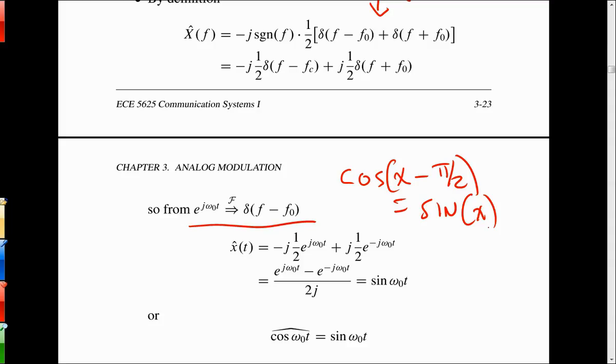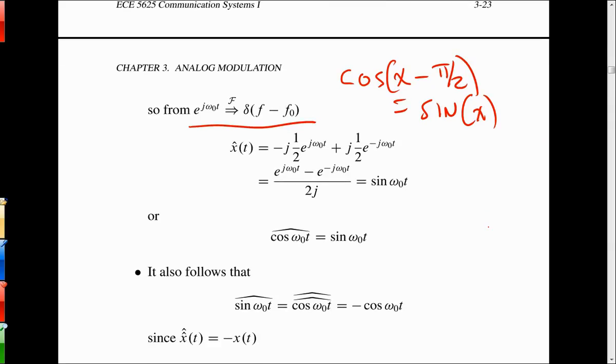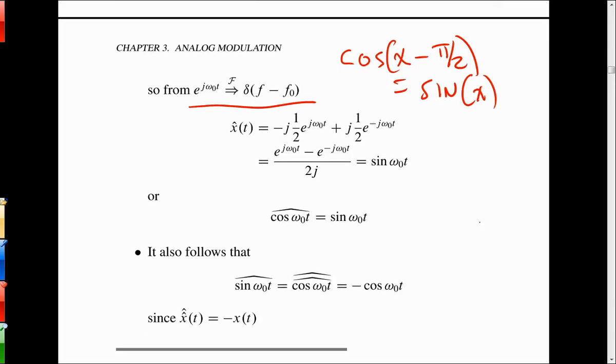You know that trig identity, right? So formally it says the big hat sitting on top, or the giant circumflex, that's the math term, remember, of cosine is sine. And then if you Hilbert transform sine, you're going to shift the phase again, and that's going to take you to minus cosine. So the big funky hat thing just means minus pi over 2? Yes, on a cosine. If it's a broadband signal, then it's more complicated what it does.